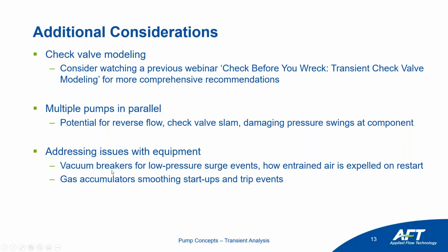We looked at gas accumulators a little bit. That can help smooth startup and trip events. So you can properly size a gas accumulator. That can help slow a trip event, make the pressure change much more gradual. Finally, sustained reverse flow. We'll leave you with a teaser for the next webinar. So if you're interested in how that works and how you can consider that in your own model, again, we'll cover that in much more depth later.